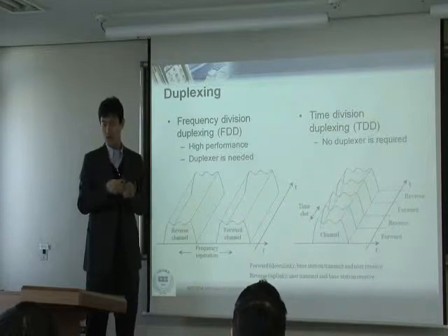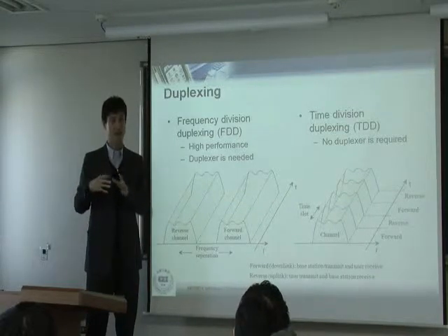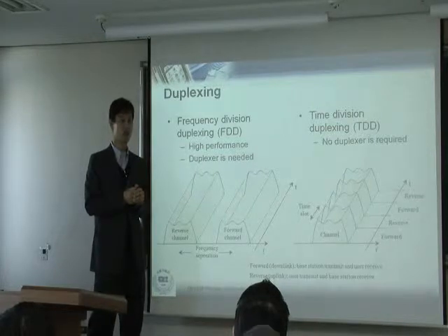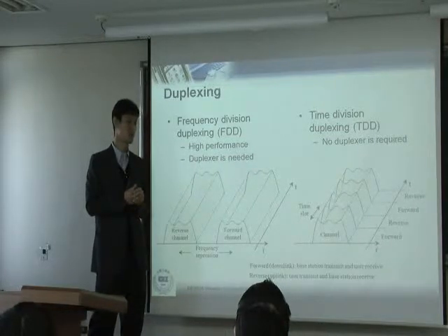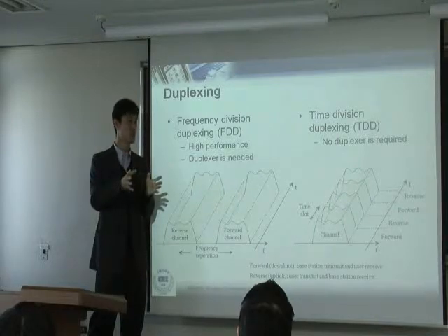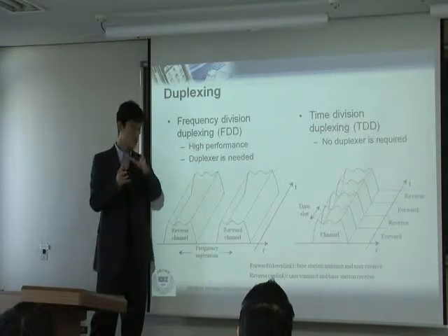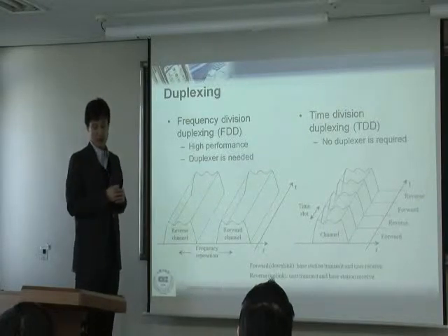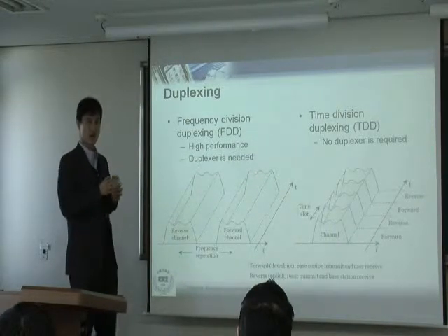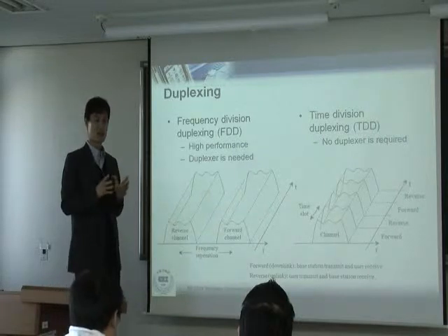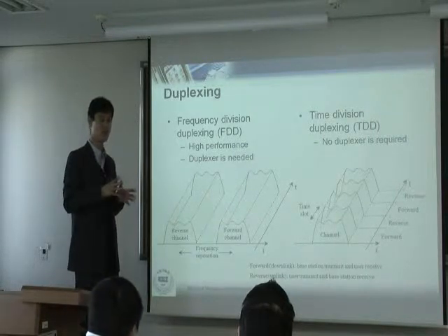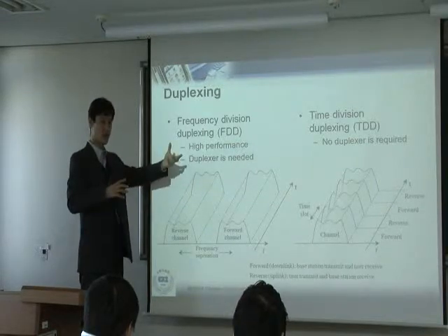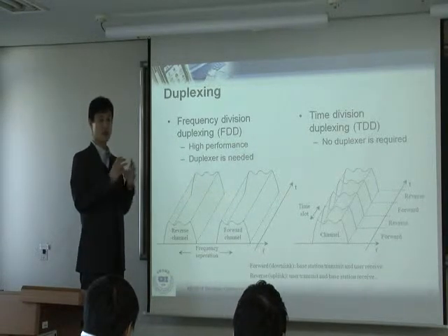If you are going to a little bit bad site, maybe your SNR goes down to minus 100, minus 105, something like that. But still your cell phone works. Still you can communicate. So now think about your receive power. Typically the noise power is like minus 110 dBm or minus 120. So compared to that noise power and considering the SNR that I just talked about, your signal power you